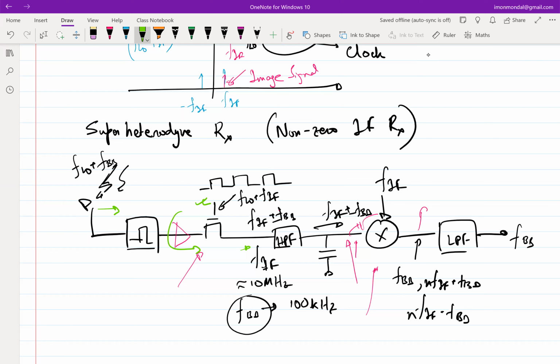So we'll simply not choose it to the frequency of the input. But then the problem is that now you have to have another set of down conversion, because after the first mixer, your output is not around DC, right? So the second set of down conversion was required, and then we eventually went into a low pass filter, and that did the job.